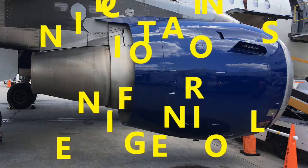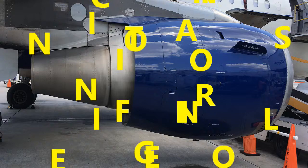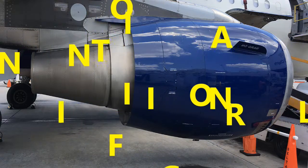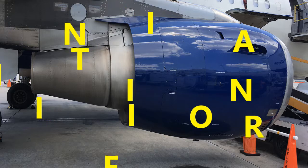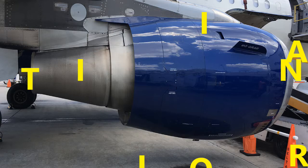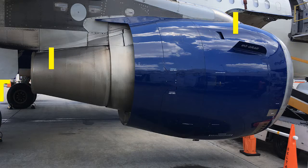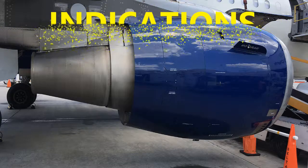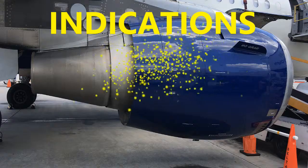The indications that you have in the cockpit. Okay, you're going to have that indication as far as the quantity of the oil. That's going to be in there. Of course, once you do the check on the oil level, if it's too low, you're going to need to fill it. After you do that, though, you need to put that warning tag in the cockpit, just to let people know it's not to be operated.